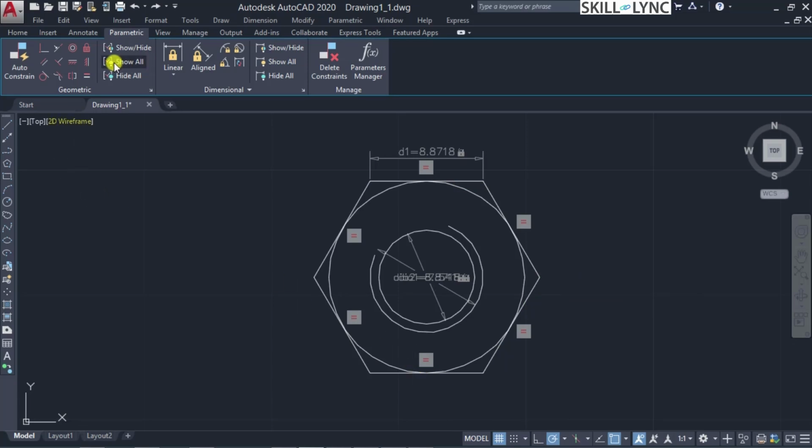It means that this polygon shape will be controlled with respect to this dimension. So next we have to constrain this circle. Wherever this dimension is going to update and this polygon is going to update, this circle that represents the chamfer cut needs to get aligned for all. So we have to assign a tangent restriction to all the contact points, that is, all the edges of the polygon.